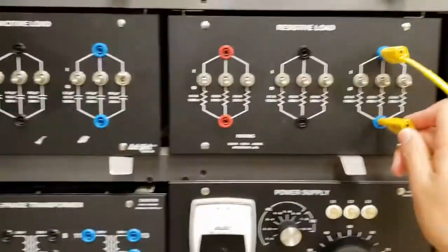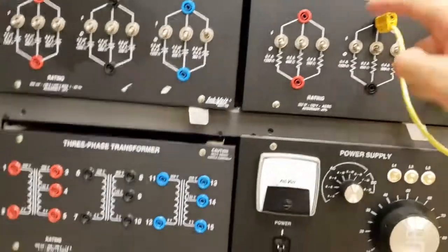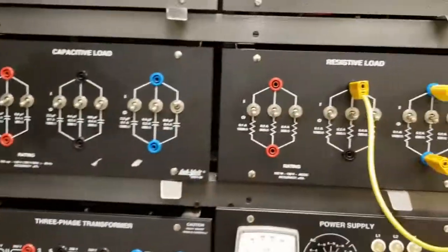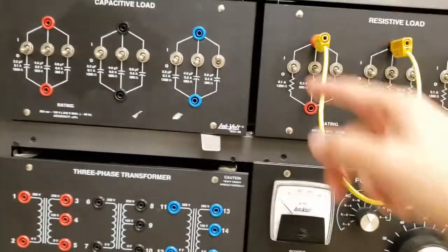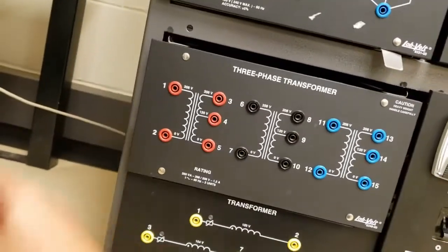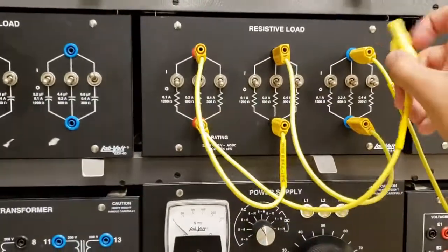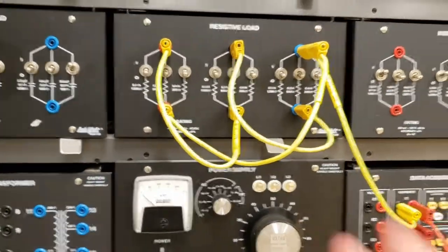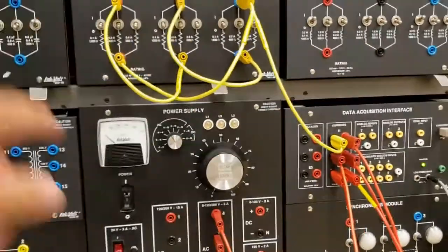So I'm gonna go ahead and do that. So 4 goes to 5, and then 5 goes to 6, the next load, also as if they're in series, and then 6 goes back to 4, like so, and that's it. That's your delta configured load. It's as if you just have 3 loads in series, kind of in a circle.